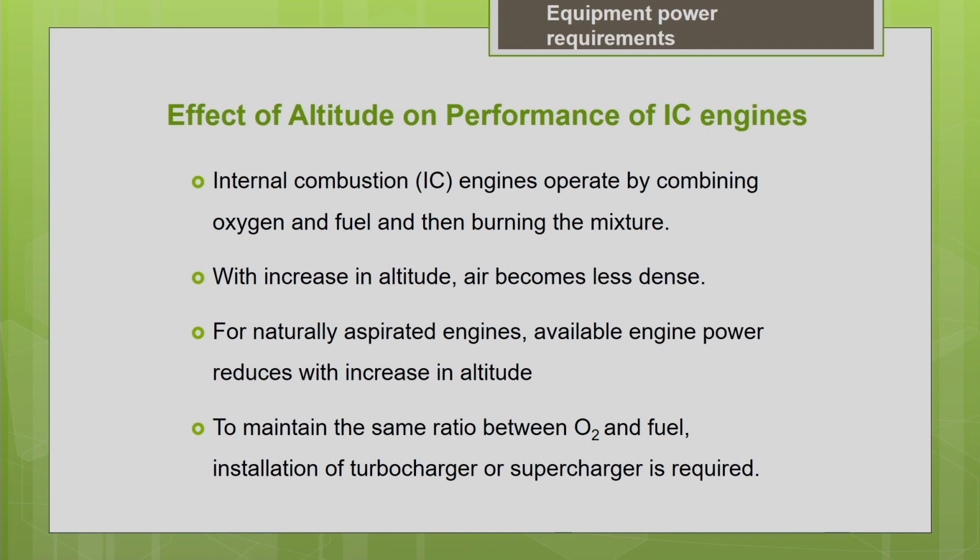Now let us see what is the effect of altitude on the performance of the engine. As we discussed earlier, the usable power depends upon the underfoot conditions, altitude and the temperature. You know that the horsepower rating of the machine is done at standard conditions by the manufacturer. They might have done the horsepower rating at standard temperature and standard atmospheric pressure. So if your project site is going to have a temperature or atmospheric pressure different from the standard conditions, then obviously the efficiency of your machine is going to be different.